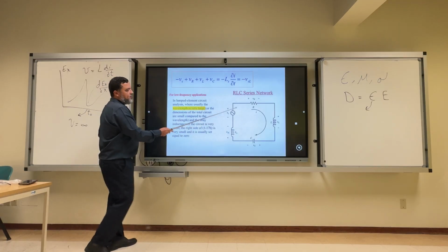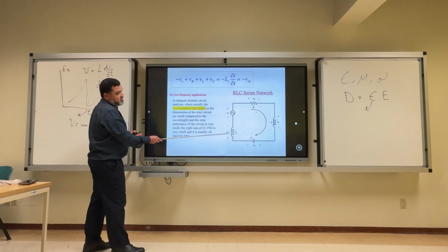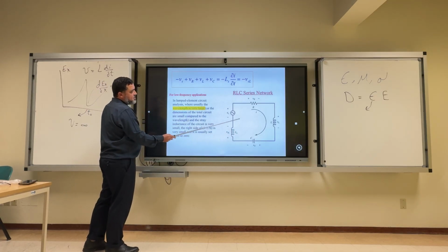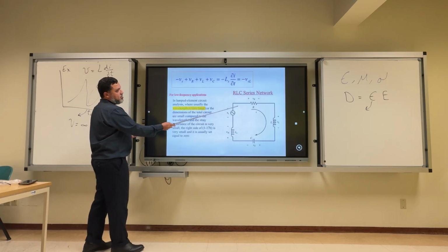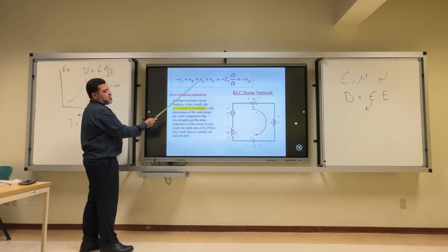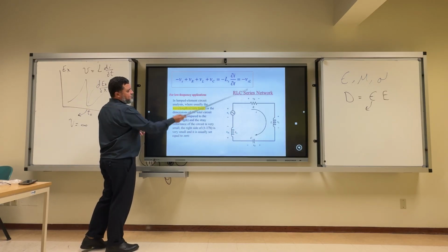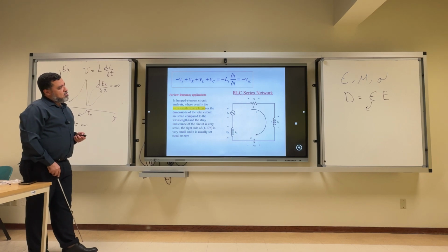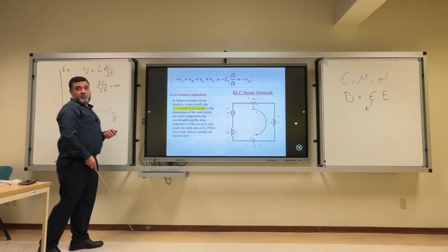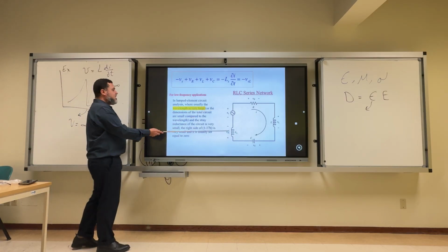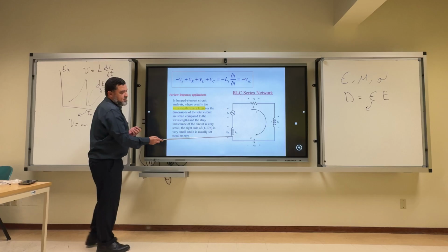In this example, we have some embraced source, an LC circuit that you added, and we have the stray inductance. So by using this relation, the summation of the voltages will be Vs plus Vr plus Vl plus Vc, all of this equal to the voltage across the inductance, right, which is minus V_Ls. So this actual inductance is added into stray inductance? Yes, this guy is stray inductance, the inductance of all these wires. This is not in the circuit; we don't add it. It's there because of all these conductors, like in the transmission line model, where we add the inductance and the capacitance between two conductors.